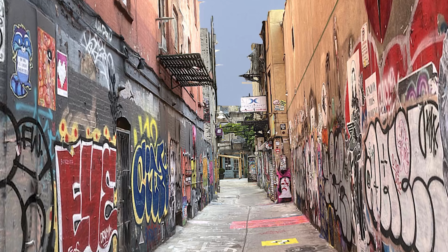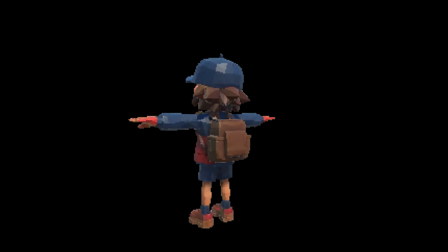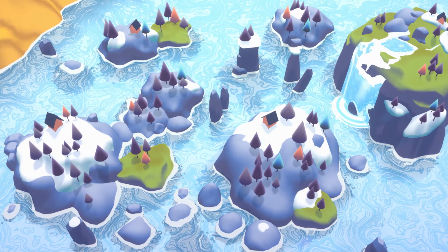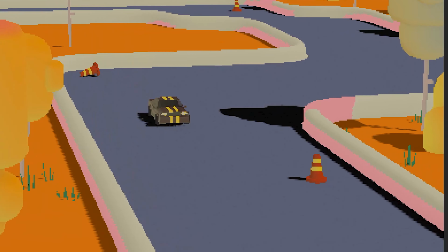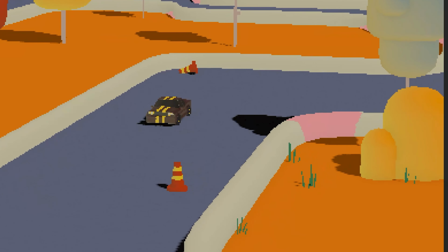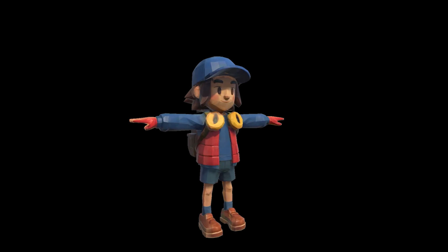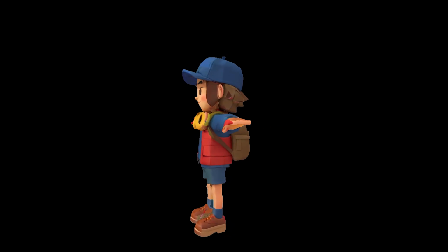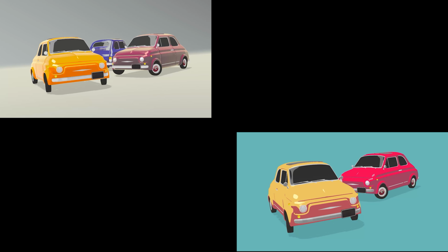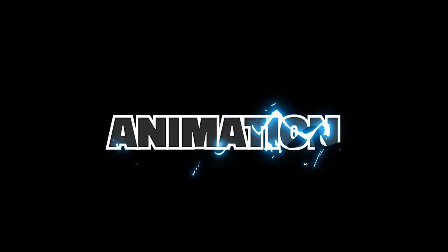Materials and textures define the surface, but something still needs to tell the computer how to render it all. That something is called a shader, the hidden instruction manual for how your material should behave on screen. There are two common types. A lit shader uses light, shadows, reflections. An unlit shader ignores all lighting, showing just the texture as is. Same mesh, same texture, but a different shader can make it look totally different.